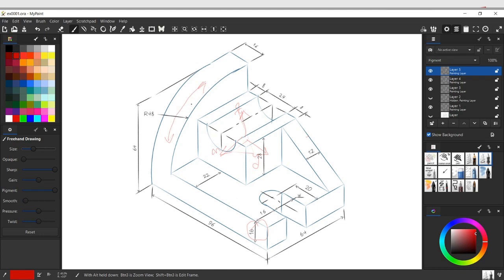And another good point is, try not to implement the fillets and chamfers in sketches. Rule of thumb: leave the detailed designs to the end after you have designed the major part of your design.